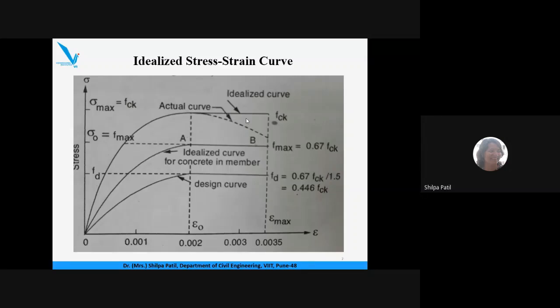They are casting cylinders having certain dimensions, and they are testing those cylinders to find out the compressive strength. Now, what will happen if we use the same material, the same cement, same aggregate size, same proportion of concrete, and still change the shape of the test specimen? It has an impact on the compressive strength value.